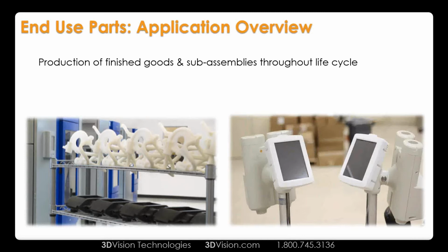So we have pilot production. Pilot production is after design is done, we've released our designs, we haven't quite got the tooling in. We're setting up our shop, putting our cells out, and seeing how they're going to be moved around the shop, what machine they're going to go on, how they're going to be assembled, what nuts and bolts we need to have in place. Once that's all figured out, we'll go into a bridge to production. Bridge to production is, we still don't have that tooling in-house, but we have a demand. We want to start manufacturing, so maybe we'll tweak the design and make it something we can manufacture and at least get a few units out the door.